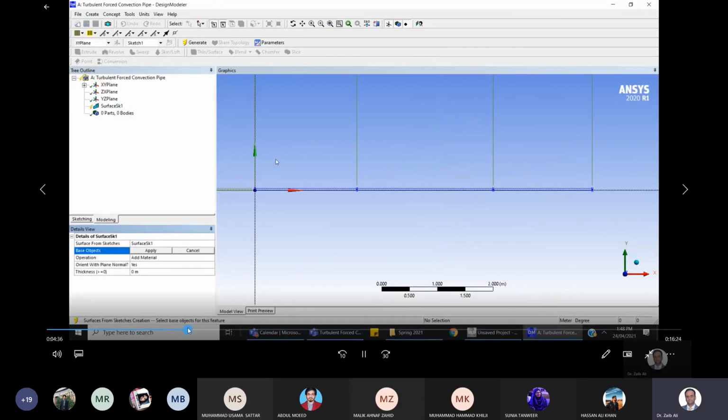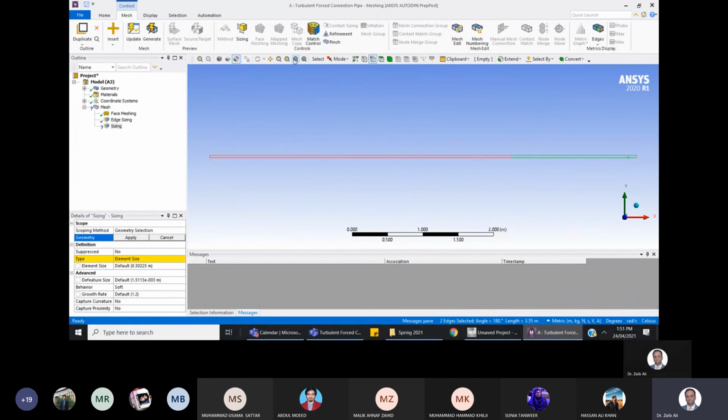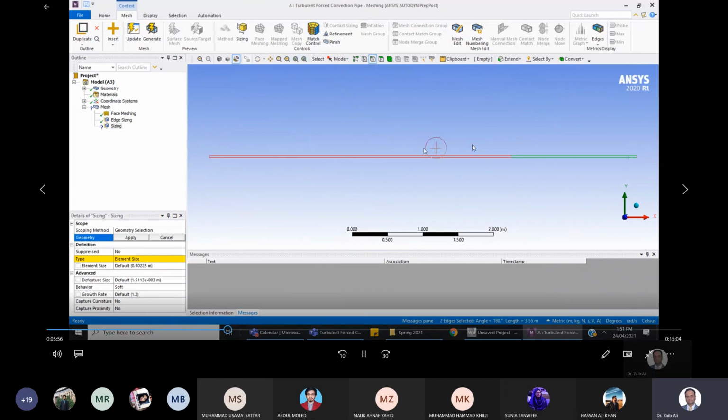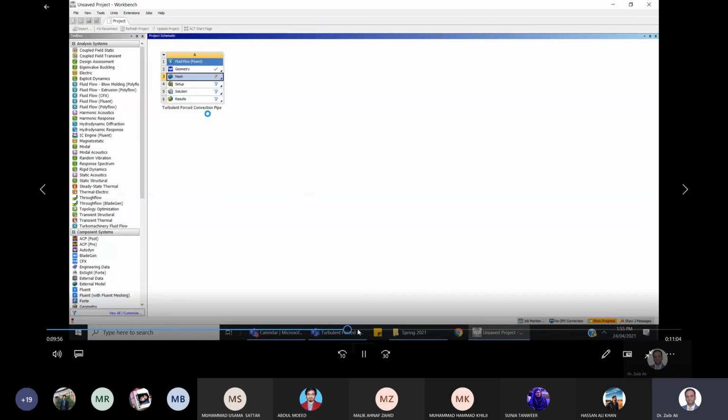So you do the usual stuff. Just need to split the upper. So we're taking the upper half using the symmetric assumption. So you need to split the upper wall into three regions. Okay, first two, so the front and rear will be insulated, and the middle will be heated. So you need to split the domain as well, so that you could prescribe the boundary conditions later.